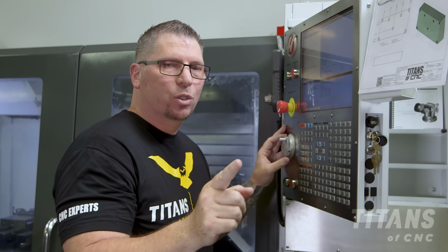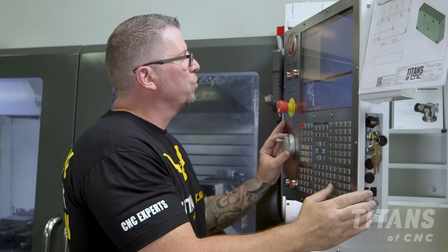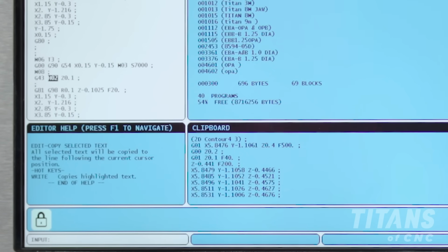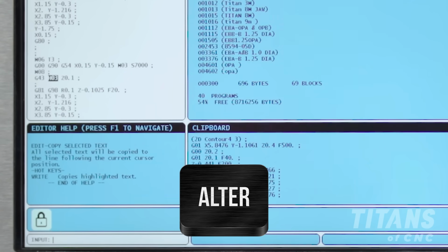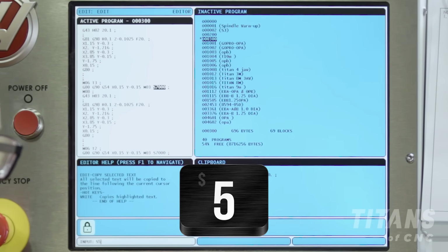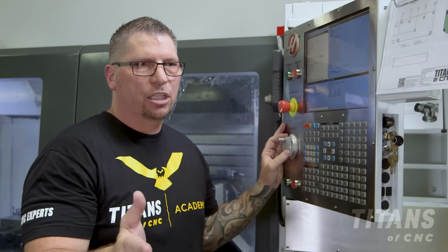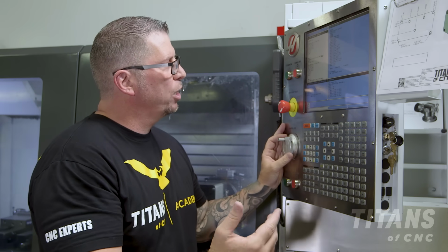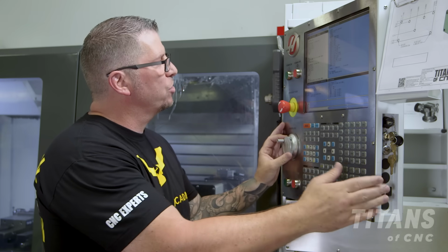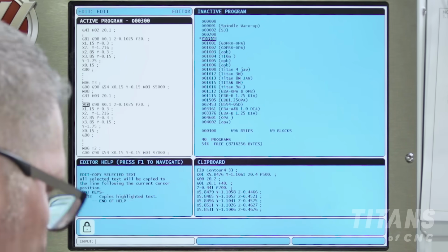And now I simply have to change my T's and my H's. You always wanna make sure that your T and your H are exactly the same, otherwise you can crash this machine. So this one's gonna be tool 3. I'm gonna hit that guy, I'm gonna hit H3, H3, I'm gonna hit that guy. I'm gonna look at it, now we're drilling, right? Let's change the RPMs a little bit. I'm gonna go 5,000. Hit that bad boy right there. We're using a Kennametal drill, so you can actually go 3 times diameter. So it's a pretty awesome drill. Just to be safe, because I'm teaching G&M code, I'm actually going to stay a little bit shy. So what I'm talking about is this. G1 is one movement drilling straight down and coming out.